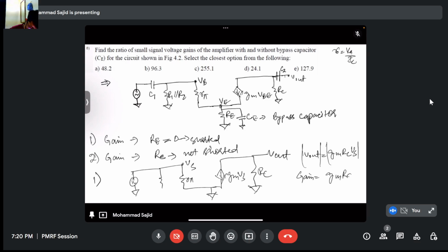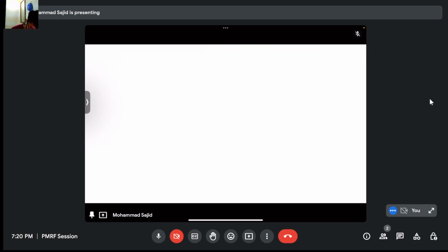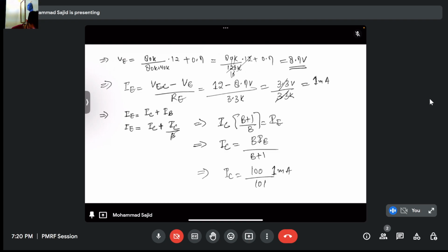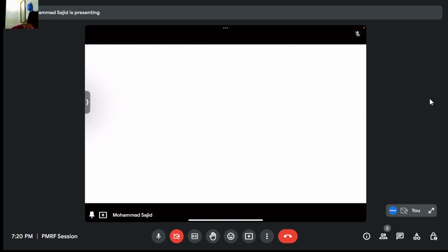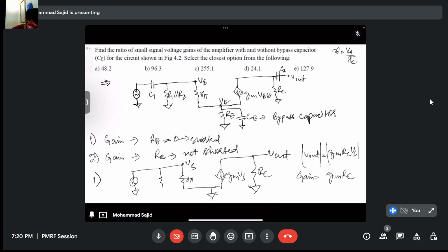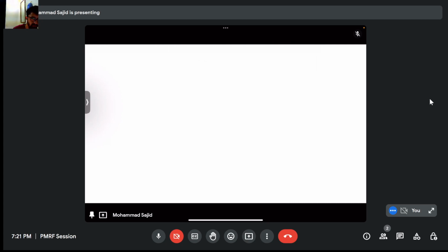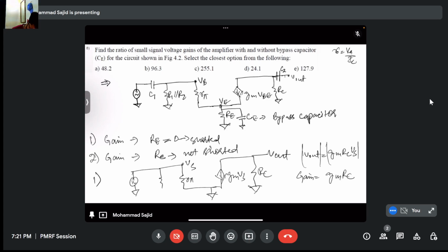Have we calculated gm for this question? No. Okay. Now RC is given to us. Let's see what gm is. gm will be given by IC by VT.